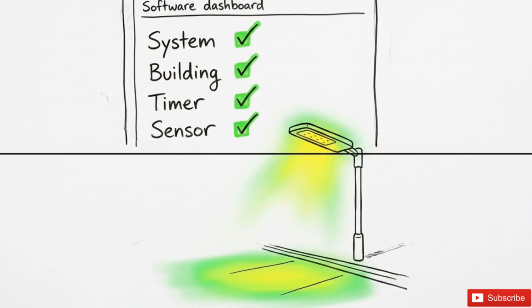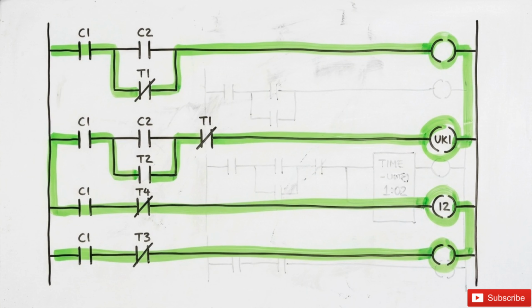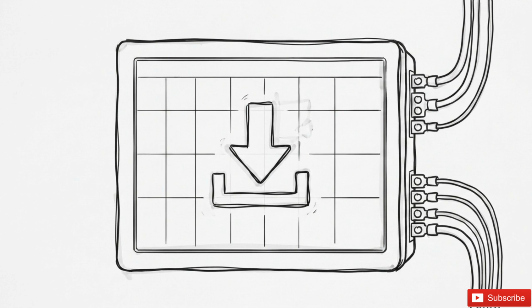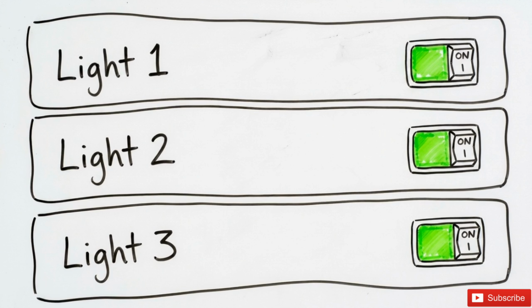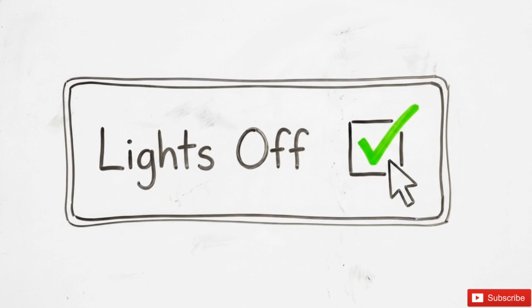By integrating the sensor input into this network, the program ensures the parking lights only energize when all environmental and timing prerequisites are satisfied. To test the logic, click Compile, then Load, and start the CPU monitoring to see the logical flow as it happens. Switch to the project view and open Simulation Table 1 to load your project tags into the simulator. Verify the baseline state. Before any inputs are triggered, interior lights 1, 2, and 3 should be in the on state. To start the sequence, toggle the Start button to set the memory latch, then toggle the Lights Off button.